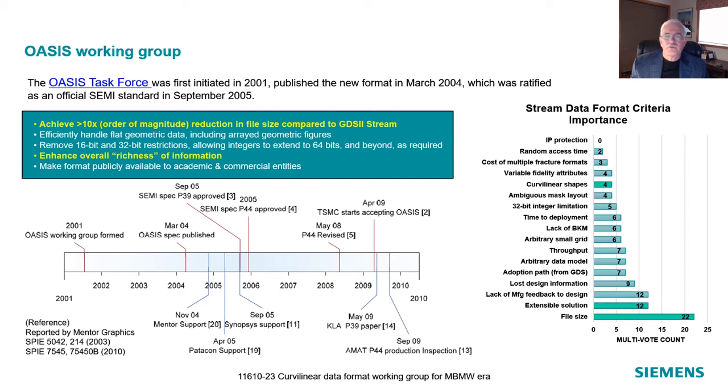P39 was well conceived, and its innovations, including the use of point lists, modality, variable integer length, coordinate offsets, implied last coordinates, 64-bit compatibility, and extensibility through the user-defined X records and through the revision process as an active SEMI format, have allowed P39 to serve us well in the ensuing 20 years.